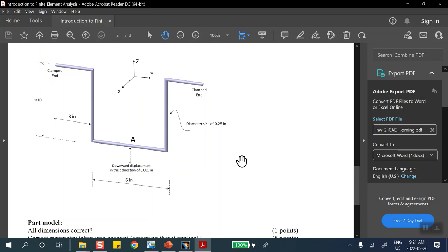That's good. So one way is, this line, don't run it like that. Just do a line from here to here and here to here. That's one way. Now, if you didn't want to do that, or if the geometry came to you from somewhere and they give you a solid object, a dumb solid, then you may not have a choice in doing this thing, but you can create a point and say, include this point in the mesh. We did that thing yesterday. Include this in the mesh, and then you can move that node down by 0.01.